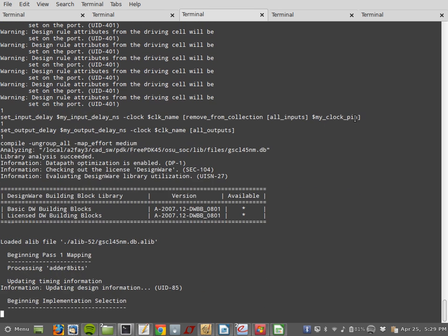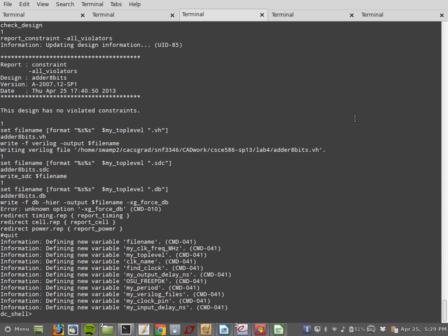When you write the Verilog file, you just write how the circuit works, like programming. When you synthesize it, the synthesizer will give you another Verilog file, but it's on the gate level. So it will give you the circuit on the gate level. That's the whole point of the synthesizer. So you give it a Verilog file, the synthesizer will give you another Verilog file, which has the gates, how the circuit is made up from the gates.